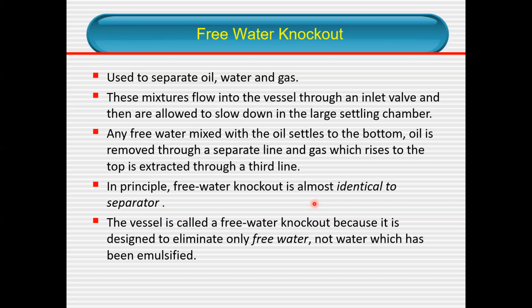Okay. Let me move to the free water knockout. We use it to separate oil, water, and gas. Actually, it is very much similar to the separator, but in this particular case, you want to get rid of the water out of the separator.